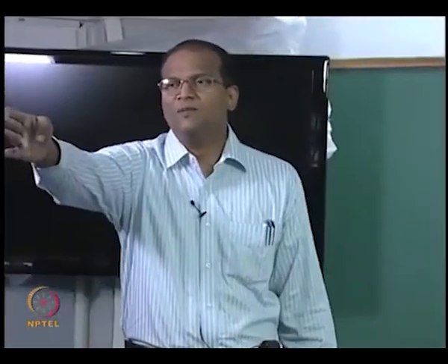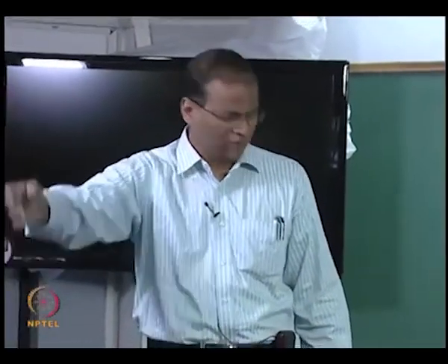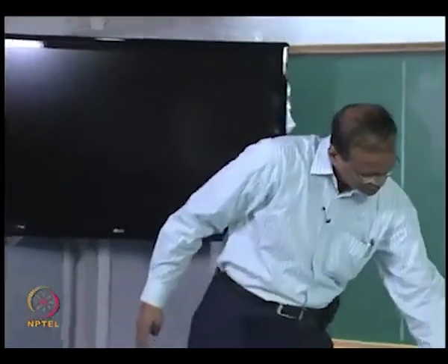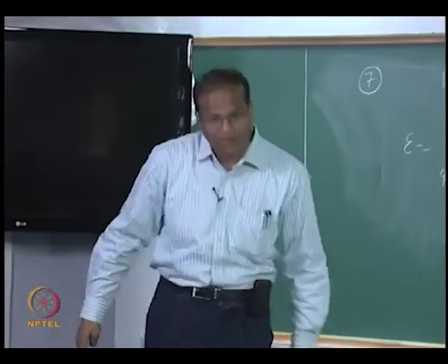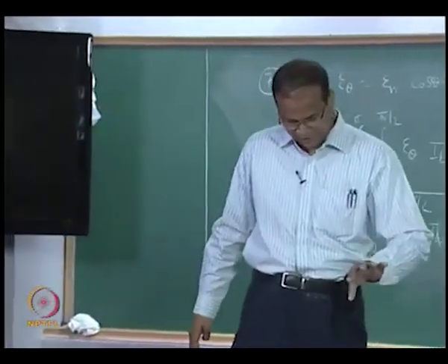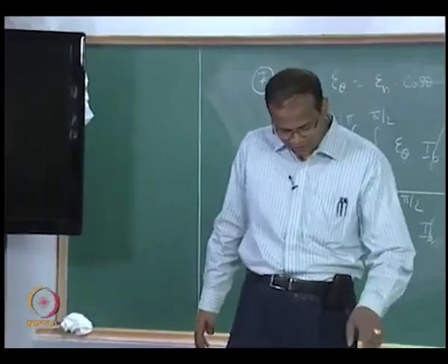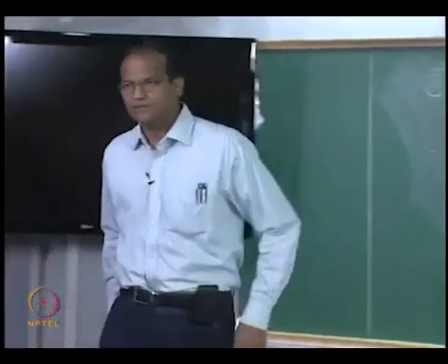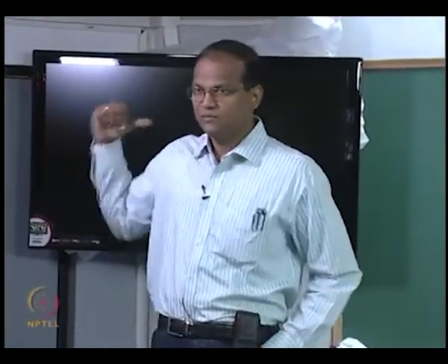So if you tell me the normal emissivity, I can give you the directional total emissivity. If you give me the directional total emissivity, I can give you the total hemispherical emissivity. Okay, it's 2/3 of the normal. But epsilon n is king. He is the highest. It is like this. Okay, so we will stop here.